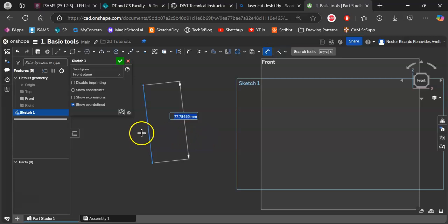In this case, you click, move, click again. In this case, it's 77, I don't know, millimeters. You can also write 7 centimeters if you want. And when you press enter, it becomes 70 because it's 70 millimeters, right? If you want to change this measurement, then you will double click on this and change it again. I can put 80 millimeters now, and it will change to 80.